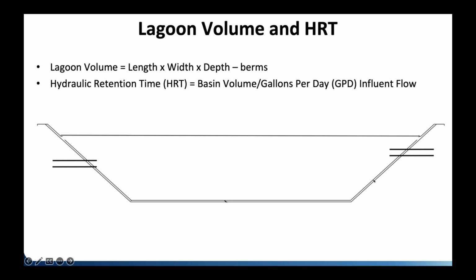You calculate it by first figuring out what the lagoon volume is. And like anything, it's length times width times depth. In the case of lagoons, you have berms. The walls aren't straight, so you have to take out the volume of the berms. A whole bunch of math I'm not going to get into here.